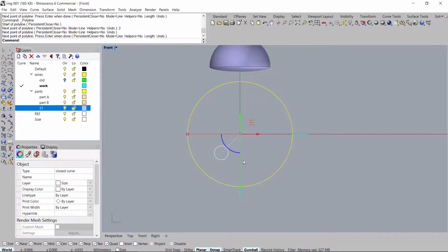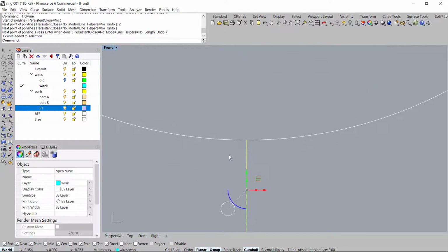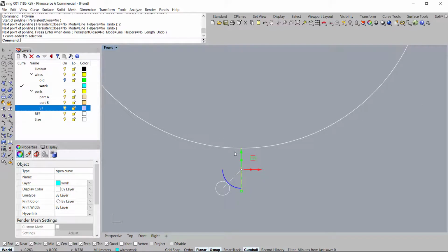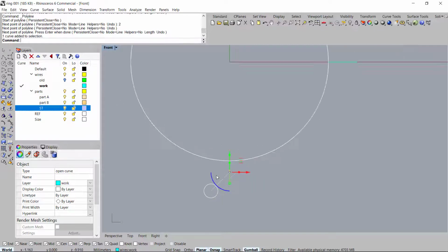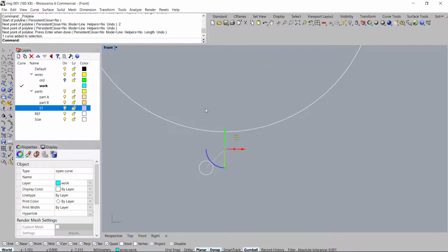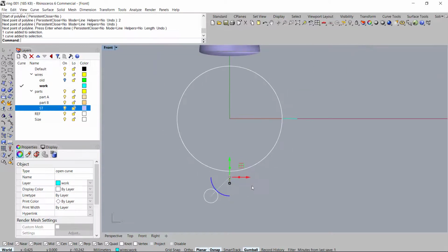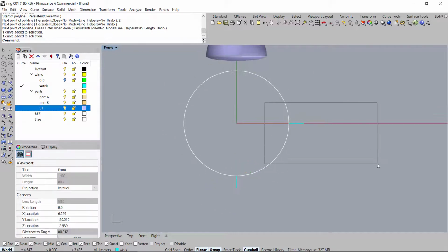I want this ring to accommodate a spring guard. The reason why I made 2 is the spring guard is usually 0.8 to 1 millimeter thick, and they sit it right inside the body here. So you do want to have at least a 1 millimeter or 0.8 thickness of metal for the entire ring. Okay, so that's the reason why I went with at least 2 millimeters. You don't have to go more than that, to be honest.